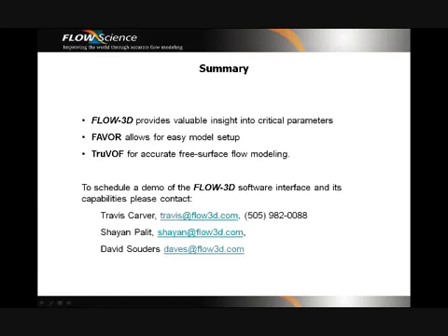I believe there are a number of parameters that one needs to define a sand-packed region, and typically these include the density of the particle itself and the solid fraction, which gives you an idea about how well the sand is packed in that area. We also look at numbers like the critical Shields number, which tells you the probability that the sand would erode given a certain flow velocity and pressure condition. So usually there are several parameters that one requires in order to define the sediment region.